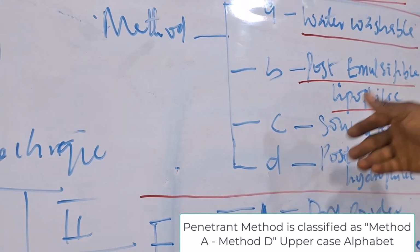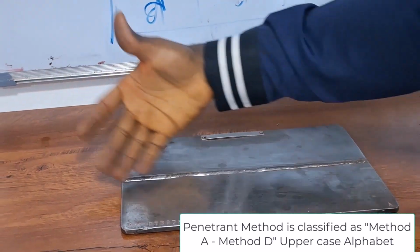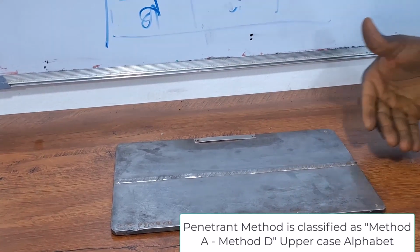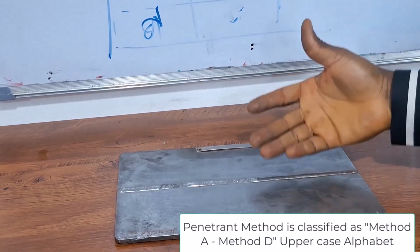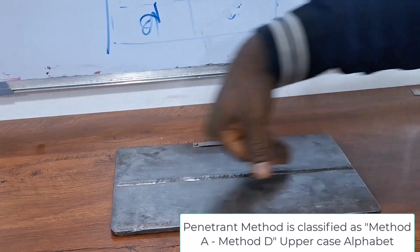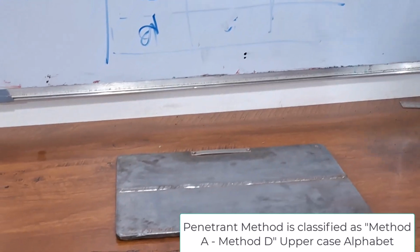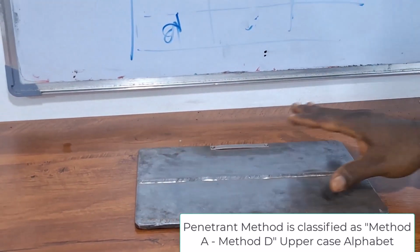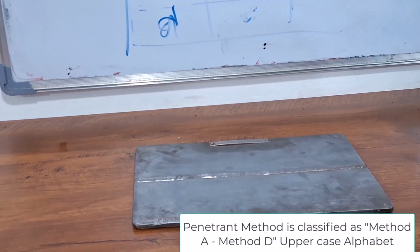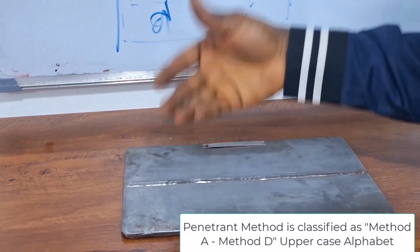So in the case of post-emulsifiable lipophilic, you apply the penetrant, which is usually a kind of greasy chemical in this case. You apply the emulsifier, the lipophilic emulsifier. The lipophilic emulsifier will now react with the excess penetrant before you wash it off. Then we have the solvent-removable, which is the one that is most common. After applying your penetrant, you allow it to dwell for some time. Then you use your remover, which is usually a solvent remover. You use it to clean off the excess penetrant.